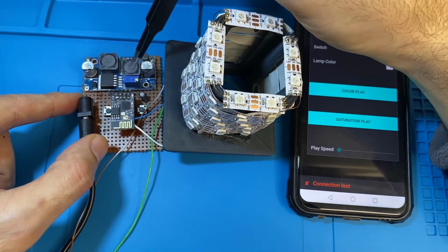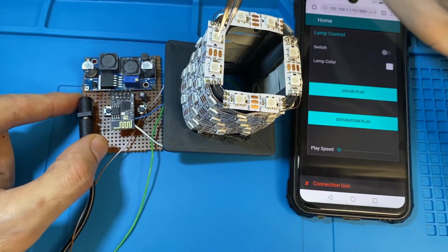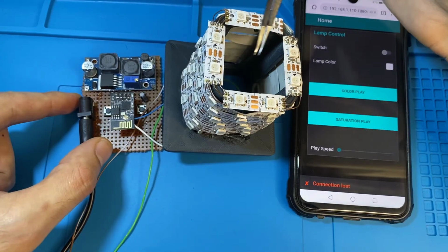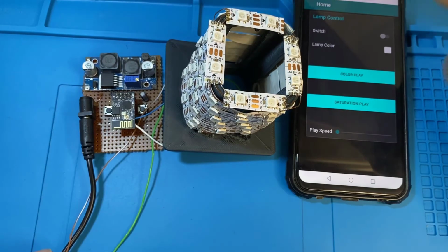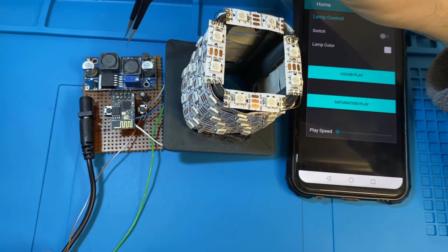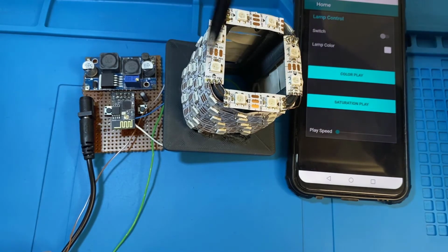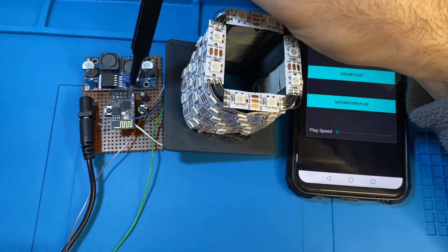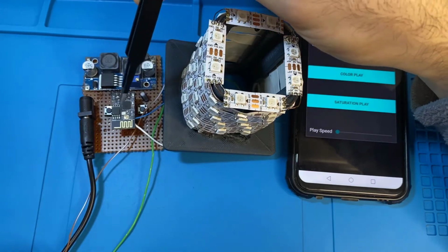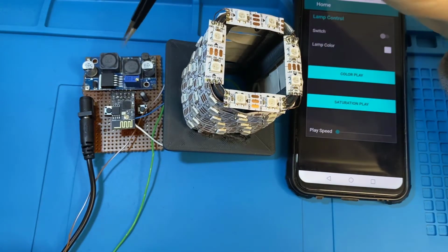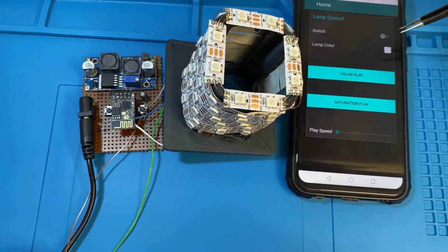I needed the 5 volt in order to supply this LED strip. Here I'm having 69 LEDs, so the 5 volt on this board is necessary in order to supply this addressable LED strip, WS2812 LEDs. And also I'm having my ESP32C3 connected to an MQTT broker on Node-RED, so I can receive commands sent from my phone in order to control this LED strip wirelessly.